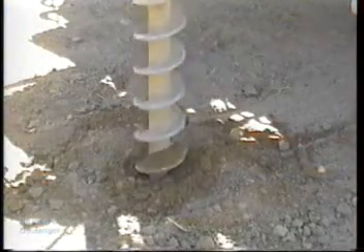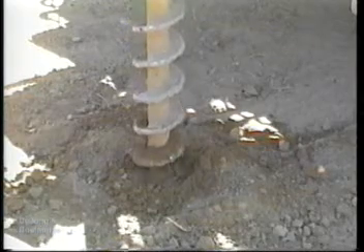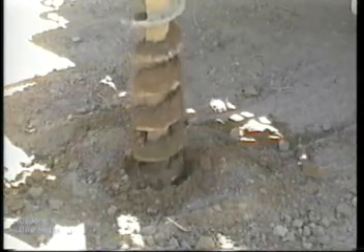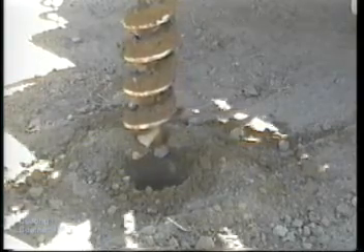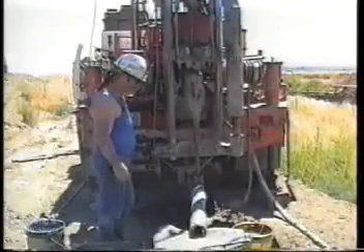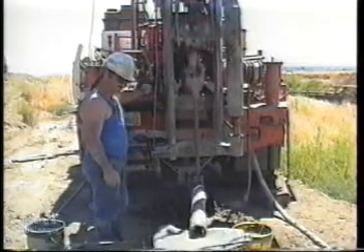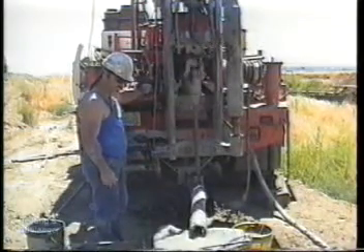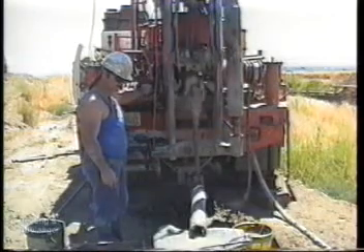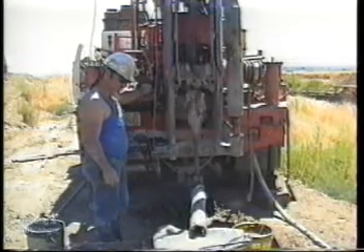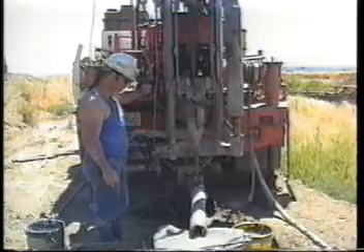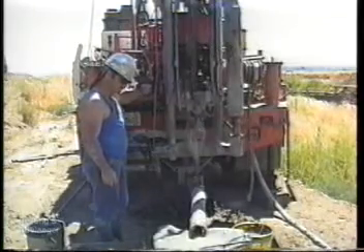It is recommended that the diameter of the borehole be 4 to 5 inches. As the diameter of a borehole is decreased, the penetration resistance is likely to increase. Side discharge bits should be used when rotary drilling because the jetting action of a face discharge bit disturbs the soil at the bottom of the borehole. Most drill bits can be modified to be side discharging by spot welding on baffles to deflect the drilling mud